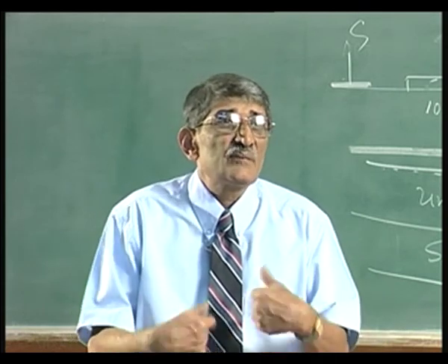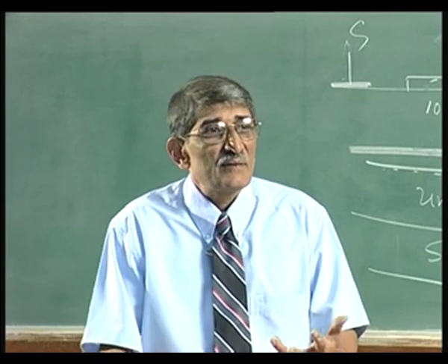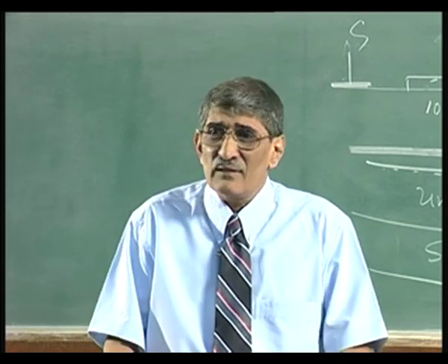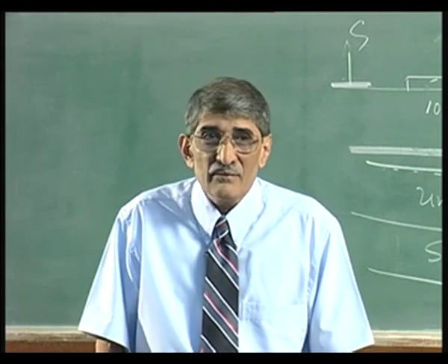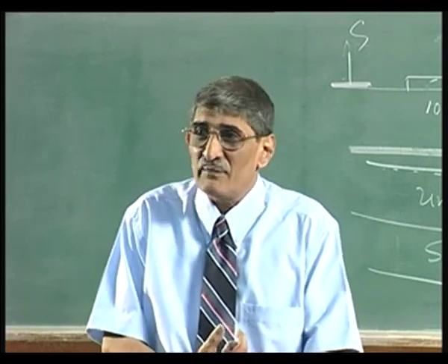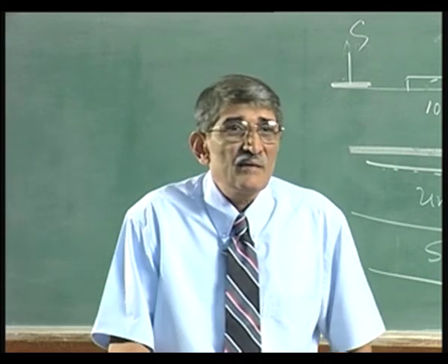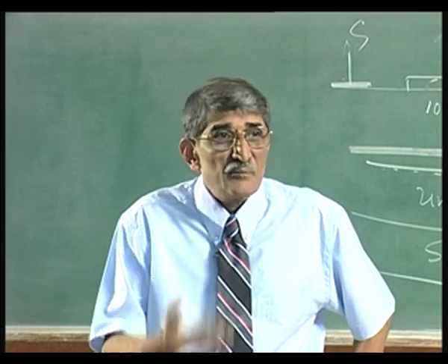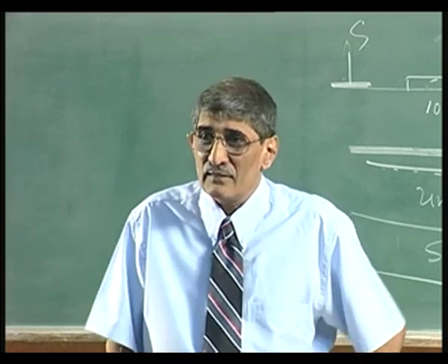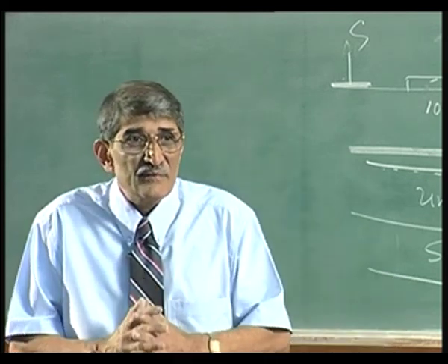On the top of that put gallium arsenide, which is the N plus layer, which you can also make delta doped, then you do not have the problem of the aluminum content. You have got 1.43 as the band gap of gallium arsenide, and you have got the gallium indium arsenide band gap as 0.75. So, you get 0.5 electron volts as the delta EC. That sort of benefit you get.